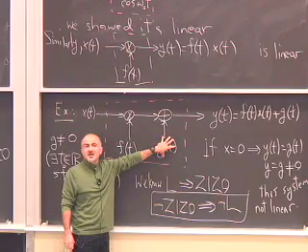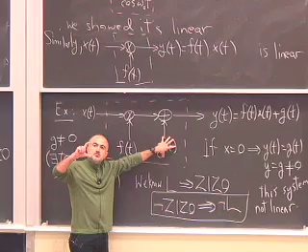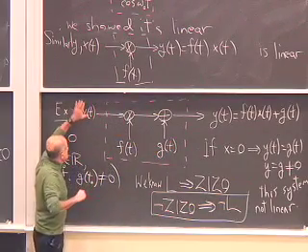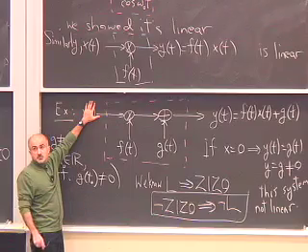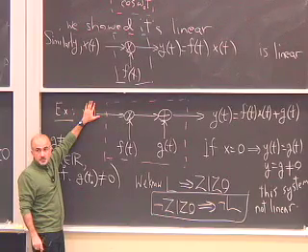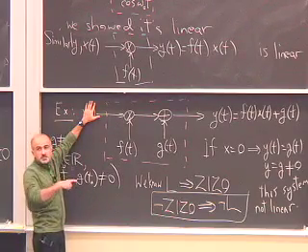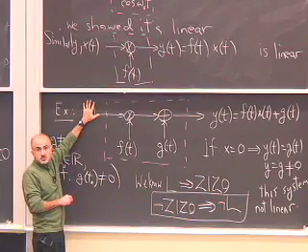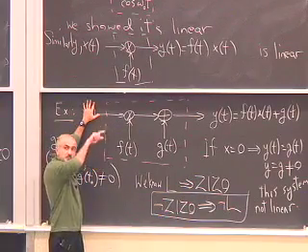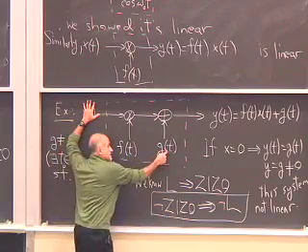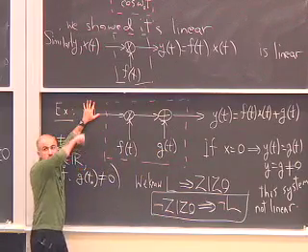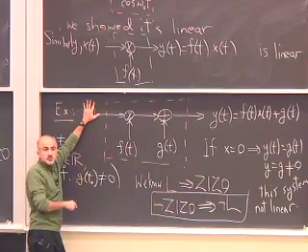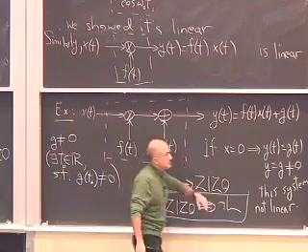So for example, if you have a capacitor that's initially charged, if I don't apply an input voltage source to the circuit, let's say I have a resistor and a capacitor in a loop. Even if I don't apply a voltage source and I just let the circuit go, the capacitor is going to have an initial voltage that's going to discharge, and so there's going to be a non-zero current through the circuit. Let me draw that.